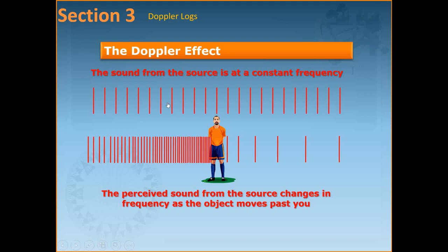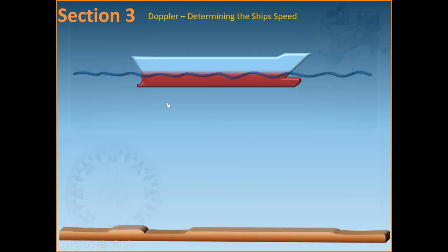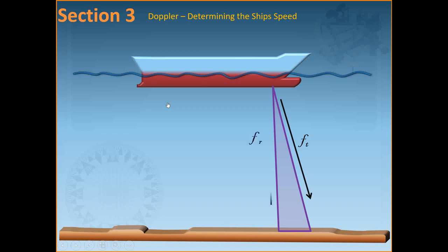So this is what we talked about before. Now if you talk about the Doppler log principle on which the ship's log is made, the principle is applied to the ship's log in the following way. A beam of sound energy or acoustic energy is transmitted from the ship at a certain frequency. The energy is reflected from the seabed or the water layer, as you will see later, and returns to the ship where it is detected and its frequency measured for comparison with the transmitted frequency.